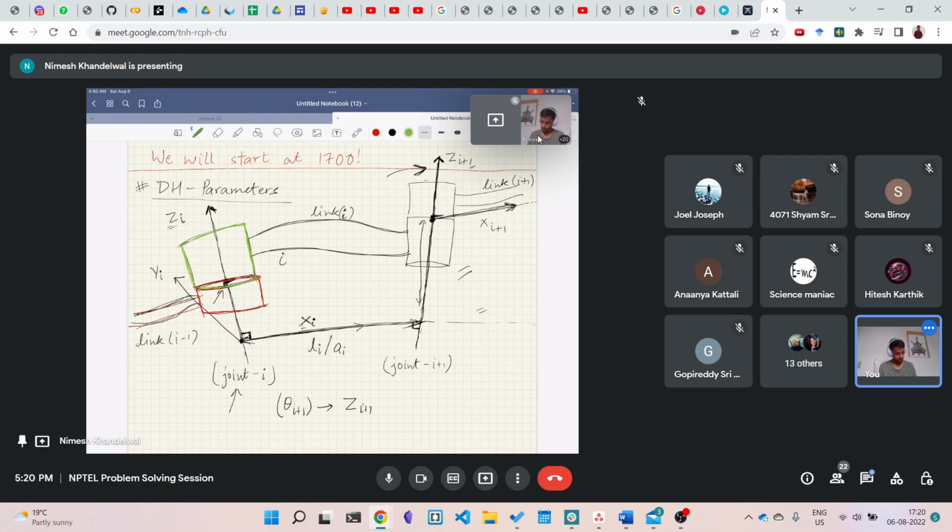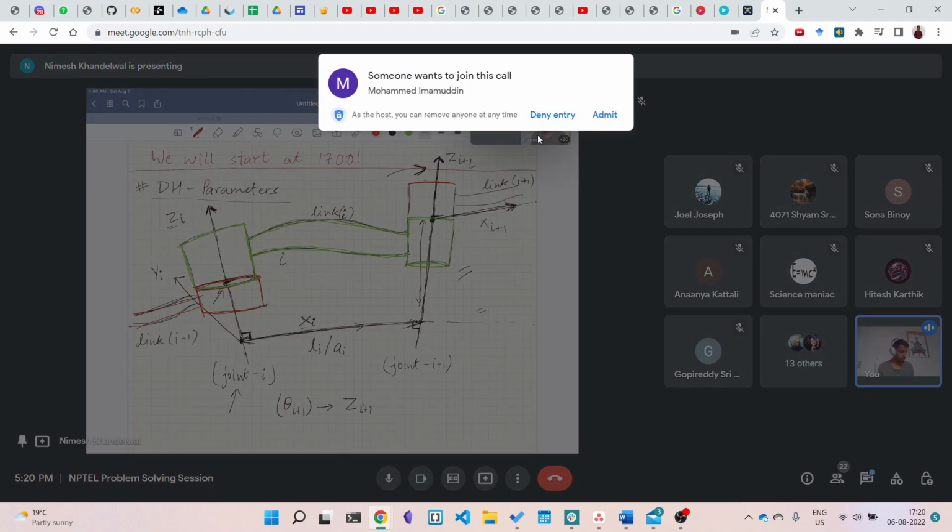So this is another link. I've not made it straight because it is not necessary that your links are always straight. But it is necessary for this convention that our links are rigid, and we have assumed all of our links to be rigid. So there are these two cylindrical connectors, you can say, at the end of each link. But the axes of these joints, these cylinders, do not necessarily point in the same direction. They can be twisted in any way they want. So this is a general case for a link of a manipulator or a robot or anything.